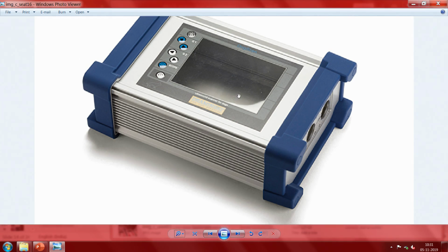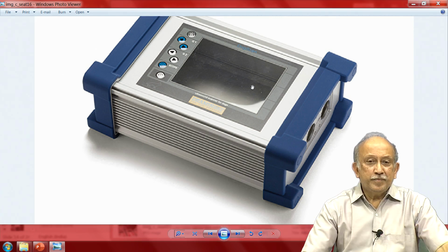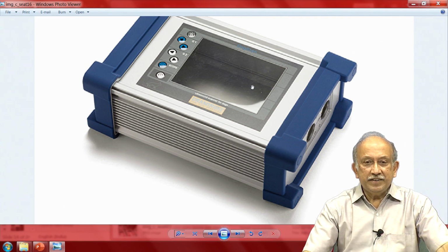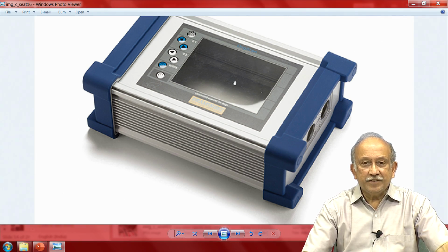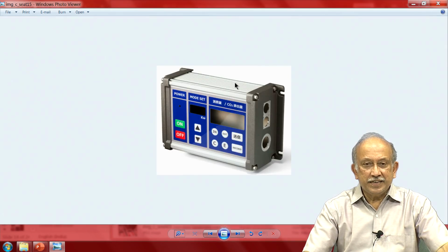Before you actually fabricate, it is very easy for you: you can just order it online, get one piece, try to push all your items inside and design the control panel. You see here, everything is under your control, you can do whatever you like. Now here it comes to the thing: do you freeze on the PCB and come here, or alternatively, do you parallelly develop this layout along with the PCB routing.